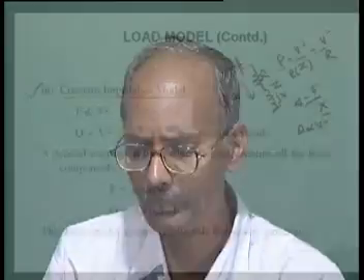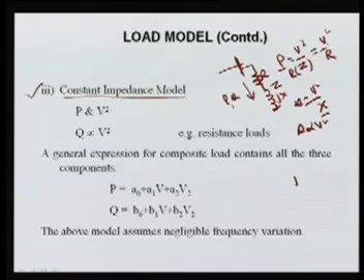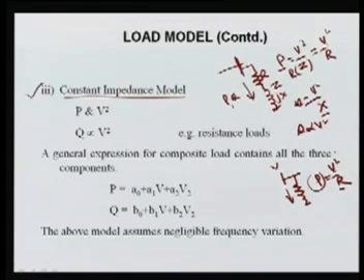If you have a load like this, for example, a simple bulb, that is a simple resistance. So you can see when the voltage is less, it gives less light. What does it mean? It means the energy dissipated in that bulb, this R is constant. The bulb is your resistor here, simply. So if the voltage of this bus is changed, the power that is taken here is converted into light. So the light power is reduced, means here V square upon R. So R is a constant, here V is changing, so here the power will be less if V is reduced, and if it is more, it will grow more.